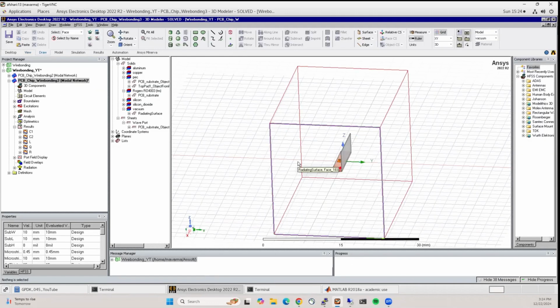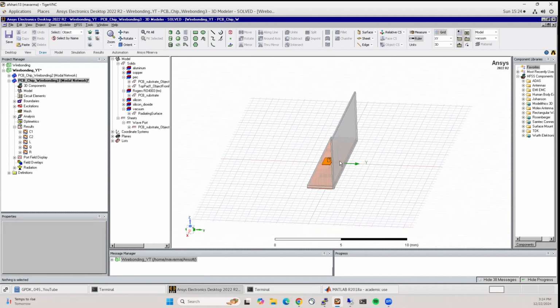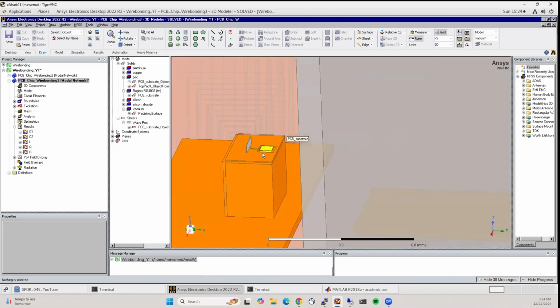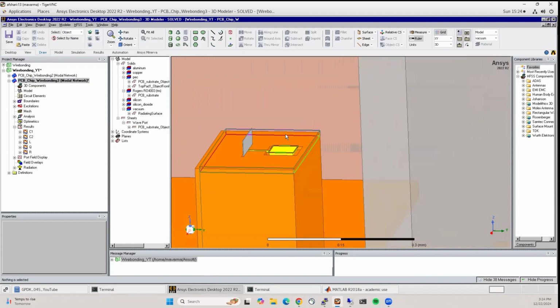I think that pretty much covers it. So now you know how to calculate the pad capacitance and wirebond inductance of a given pad. Of course, if you only care about the pad, then it's fairly straightforward. You just use a one-port network, and then you do this simulation, right?